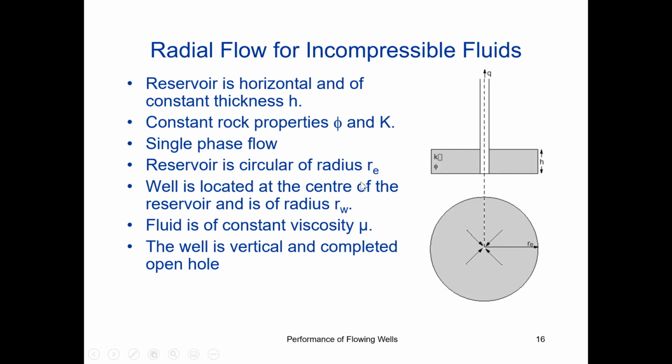So we need to change Darcy's equation based on radial flow. If we have an incompressible fluid, it means that density and viscosity don't change because it's not compressible.